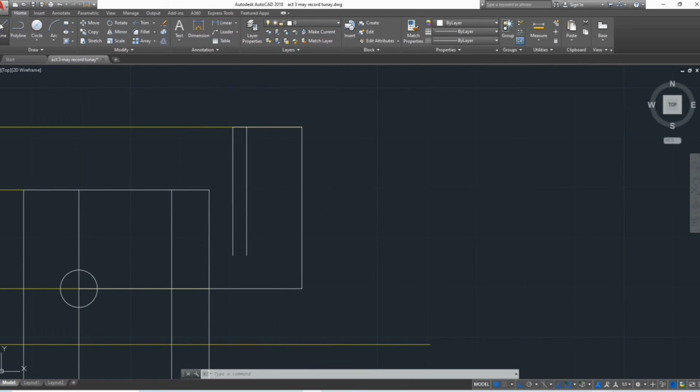And then draw another line or just connect it to this point. And then extend this line until it touches the vertical line. After that, draw a guideline again on this part, measuring 0.265, then enter.